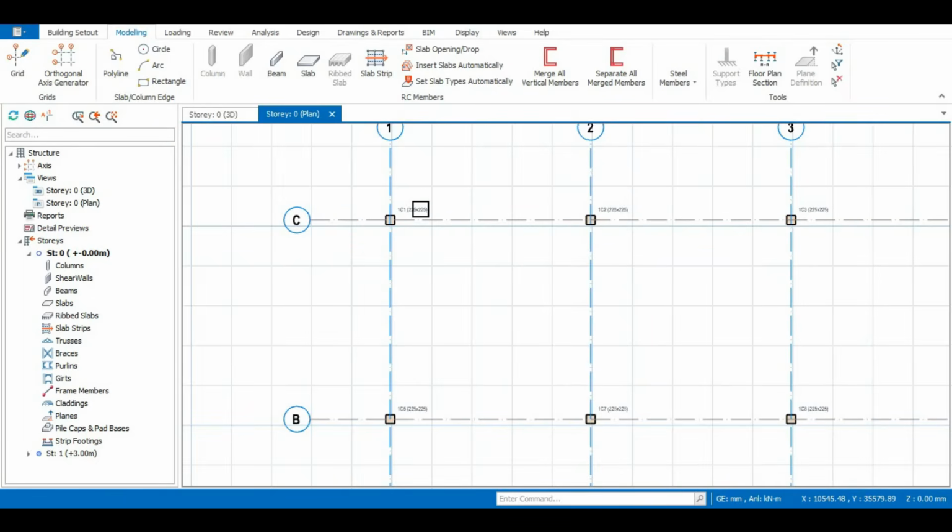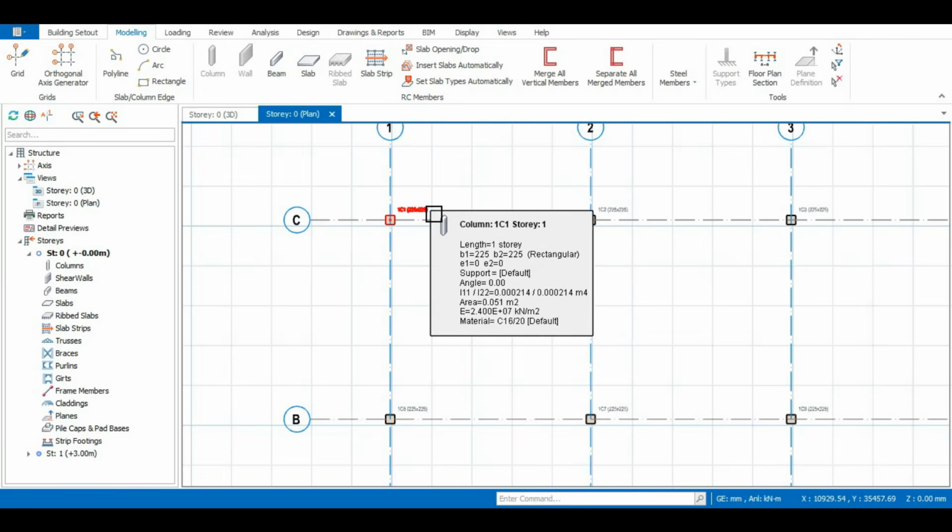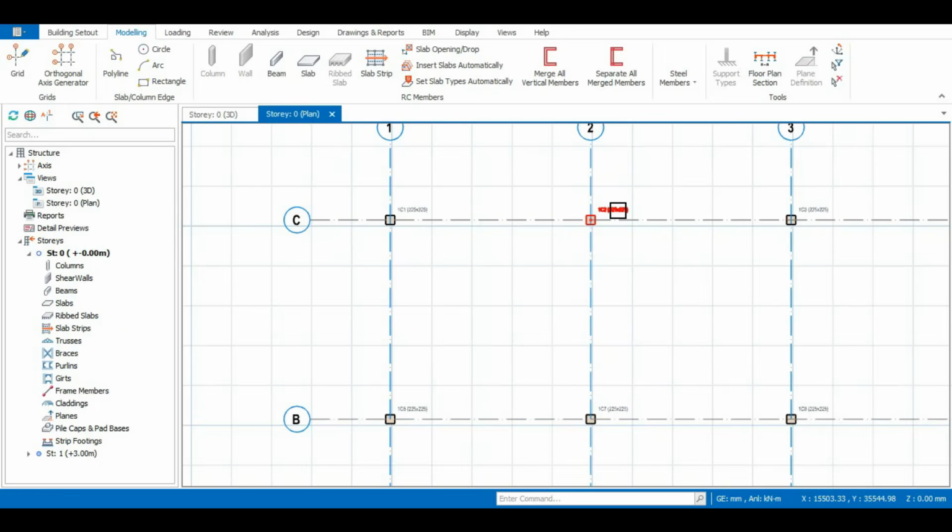And if you are designing a pad foundation, you don't just design it based on the fact that you just want to design a foundation. You design pad foundation based on the recommendation of your soil test or the nature of the soil in the area where the project is going to be executed. But it's always more advisable to design based on the reports of the soil test.